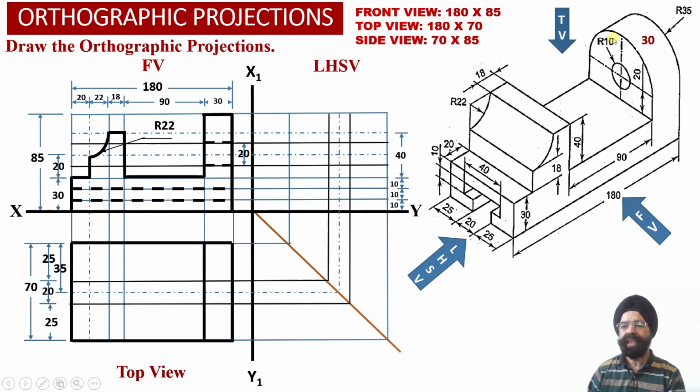Now we also know that the width of this vertical web, which happens to lie perpendicular to the front face of the solid towards the right hand side portion of the solid over here, happens to be 30 millimeter. So the top view projections corresponding to this vertical web will be obtained as apparent shape rectangular projections into the top view projections over here. These rectangular projections are not providing us with the actual shape of this semicircular vertical web.